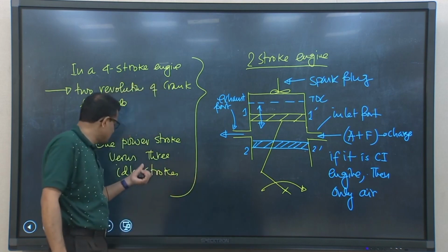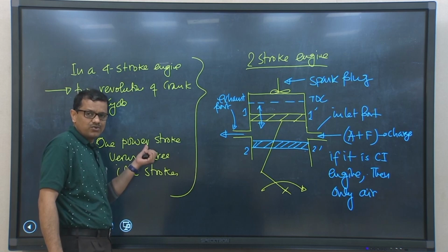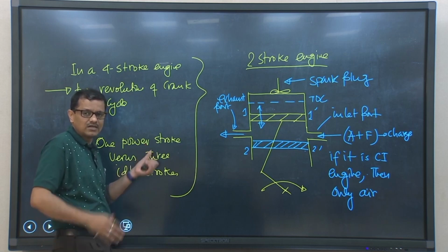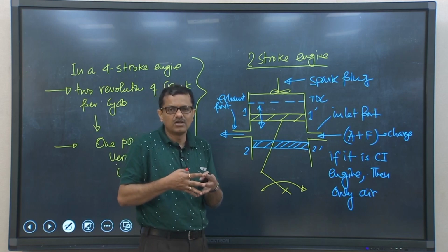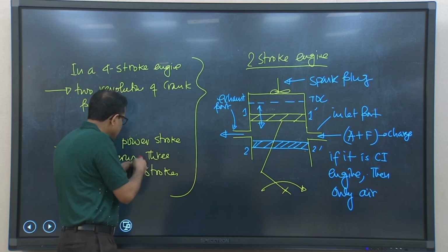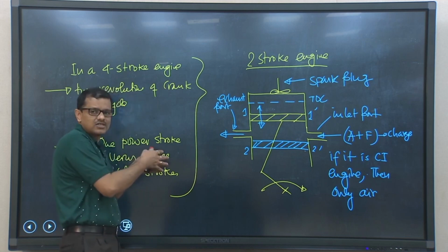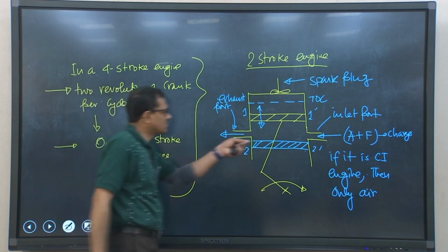So, the engine is getting sufficient time to cool down. Here we have 3 idle strokes for 1 power stroke. The power which is produced inside the cylinder will definitely increase the temperature of different parts of the engine. And since in this case there are 3 other idle strokes, the engine is getting enough time to cool down, but in a two stroke engine it is not the case.